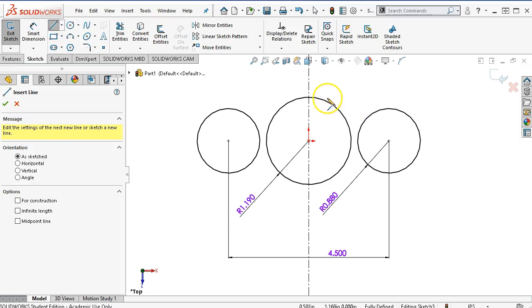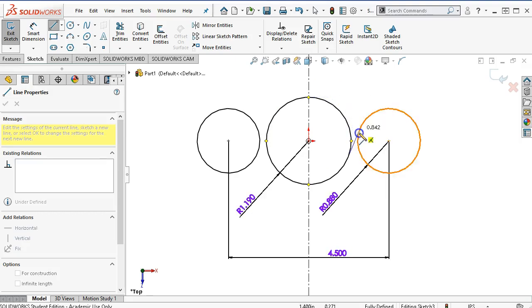All right, so setting our tangencies. Sometimes we want tangency, sometimes we don't. So if we don't want tangency, usually I'll pick a way and try to just get coincident. But in this case, all right, it went that way, that's fine. So if I achieve tangency, then it's going to follow that circle all the way around. If I don't, I will see a normal coincidence. And then notice my yellow box went to coincident and to tangent. So we'll try that again.